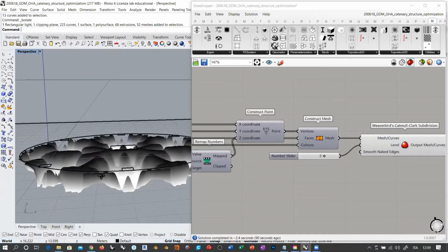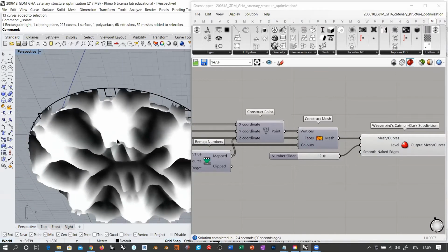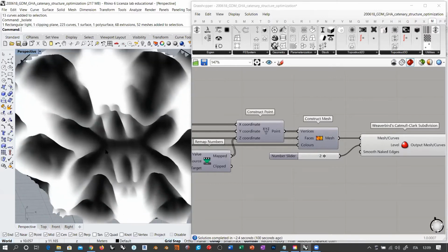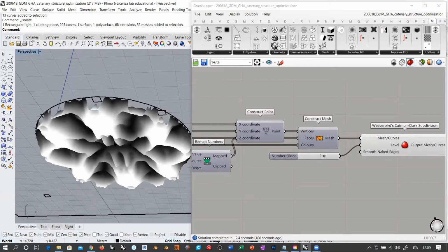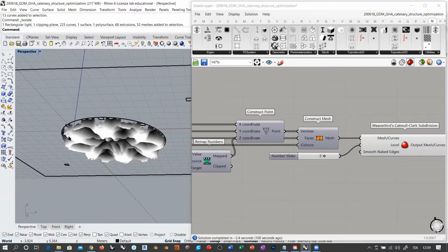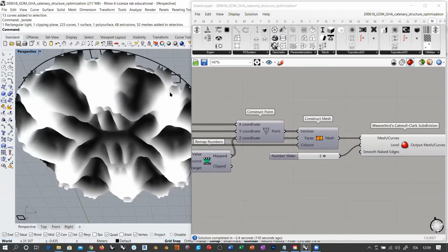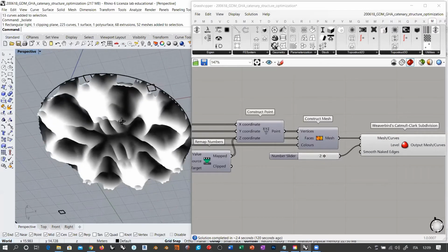This means that if you consider this as a solid object, then eventually you will have a variable thickness that depends on the distribution of the stress lines inside this membrane. So if we place columns where these points are, and if we apply a load here at the center, this thickness, in a compression resistant material of course, is going to be good for bearing the load that we apply in this area on top of the membrane. So that's the idea. Okay.